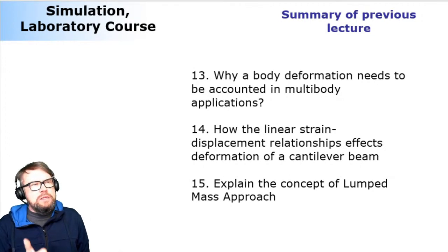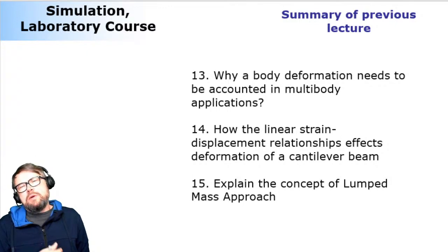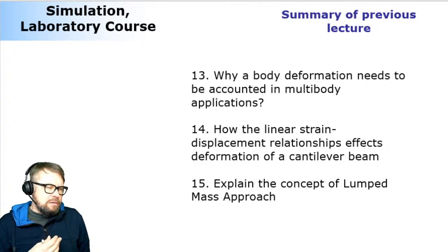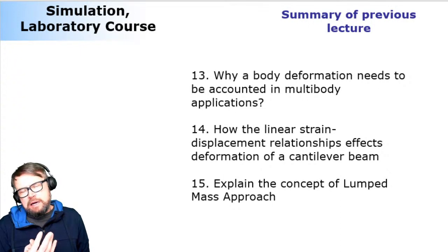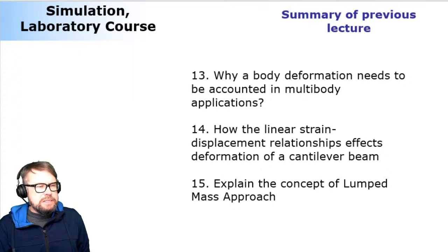So if you are dealing with rigid bodies, of course, you cannot make any prediction about the strains and stresses. And strains and stresses in turn are important when you're figuring out what the dimension of the structure is supposed to be. If you're making predictions about fatigue life, then you need to know the loading stresses. And you can only get them when you are considering the structure to be flexible, deformable.